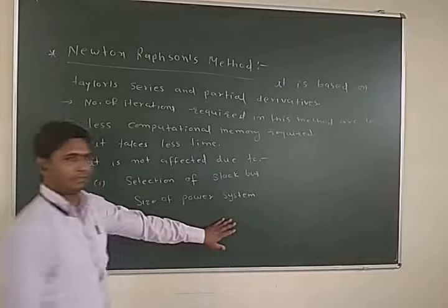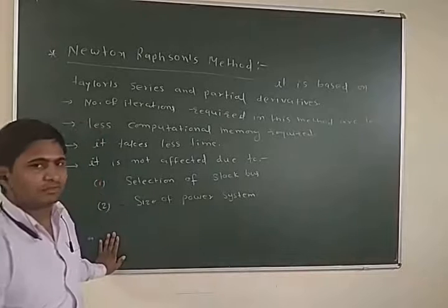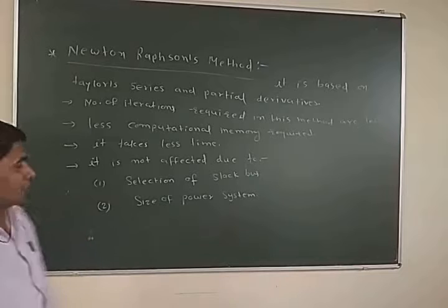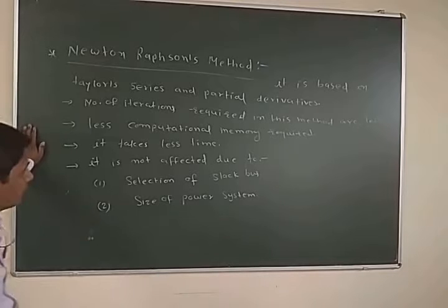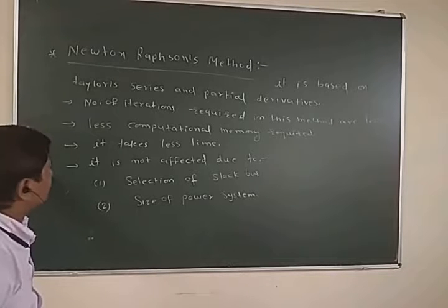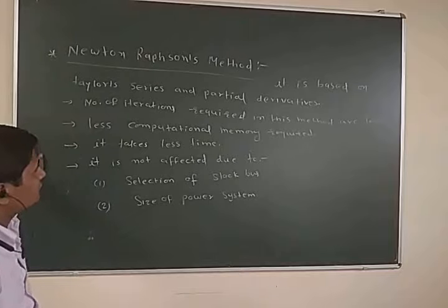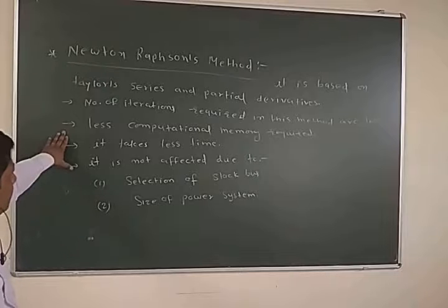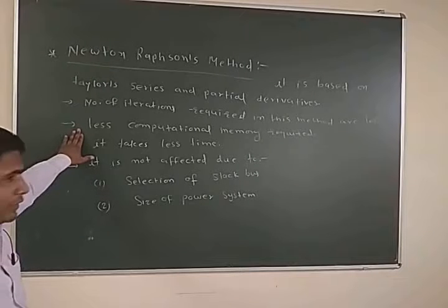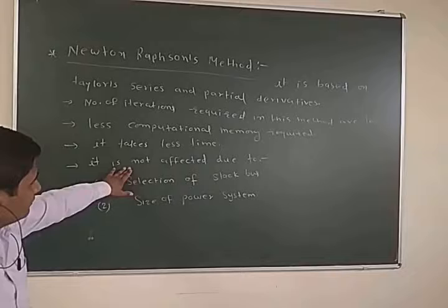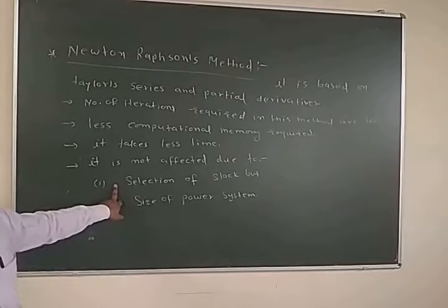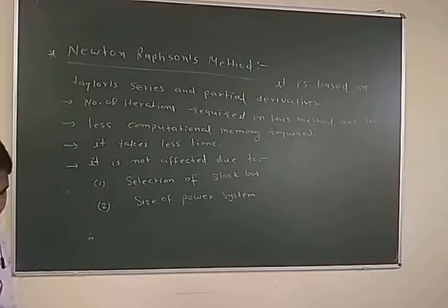So this method can be used for large power systems for the solution of nonlinear equations in load flow analysis. So this is the basic about Newton-Raphson method, in which we use Taylor series and partial derivatives, and it takes less memory and less computational time, and it is not affected due to size of power system and selection of slack bus.